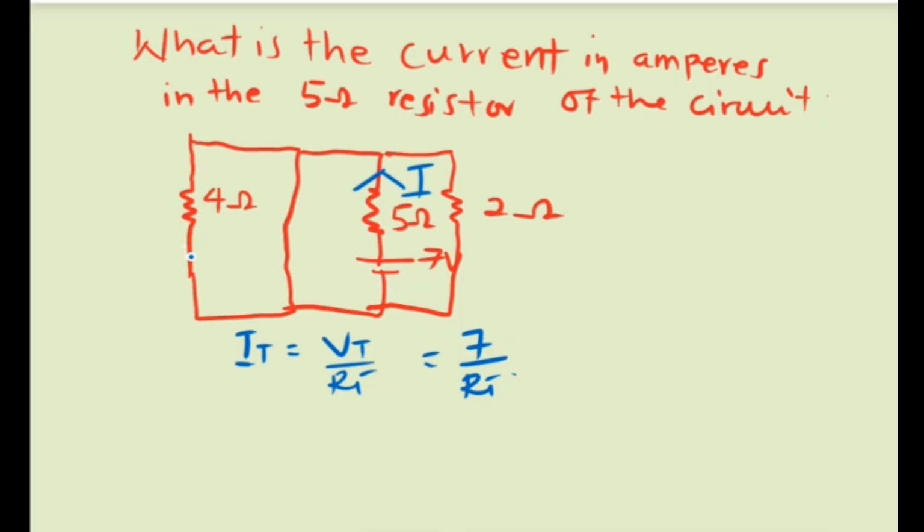When it sees this 4 ohm, and this 2 ohm, and then there is nothing here, it will rather bypass them and pass here back to the circuit. Meaning that this 4 ohm and the 2 ohm have been short circuited, and hence the current just takes this path and comes back to the source. Let's redraw the active circuit, then find the total resistance.